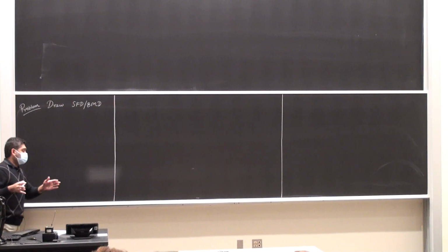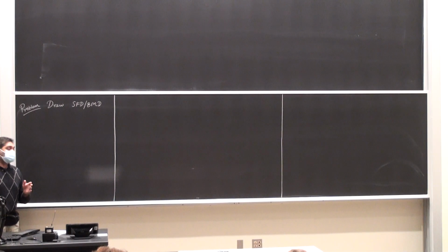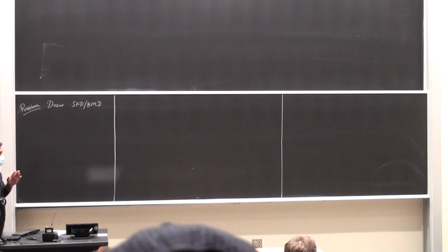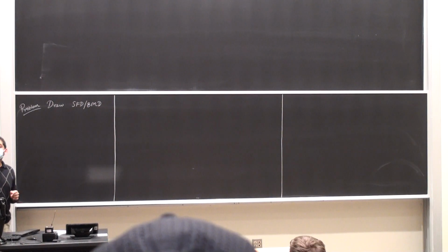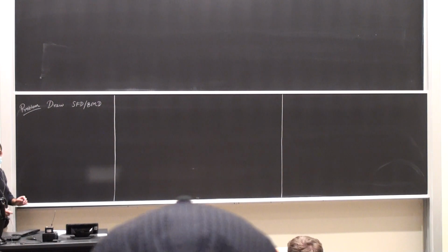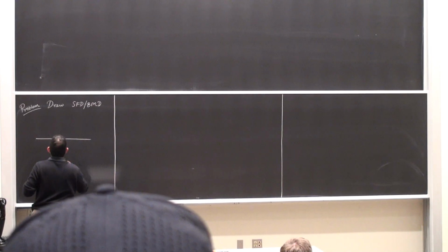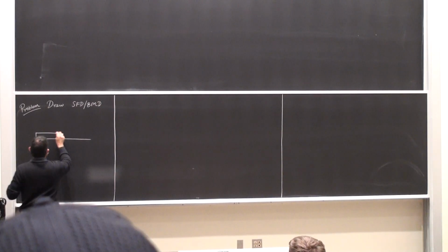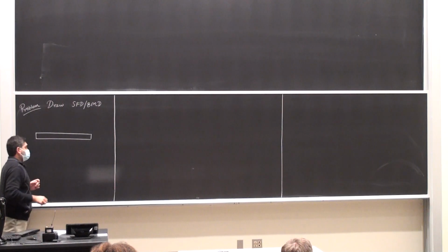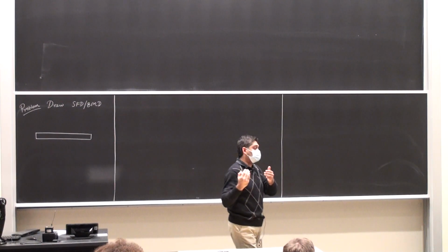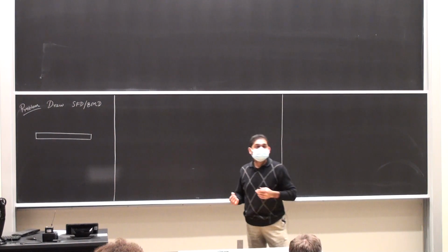And I'm probably going to take only one problem and solve it today, but I want to do this very carefully, properly, so that if you know how to solve this problem, you should know how to do shear force and bending moment diagrams. Okay? Alright, here's the problem. I have a simply supported beam. A simply supported beam is a beam with a pin support at one end and a roller at the other.